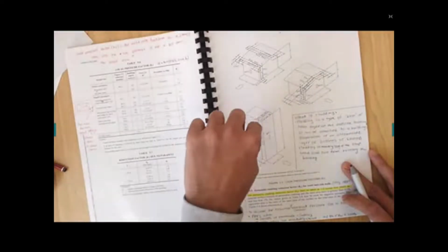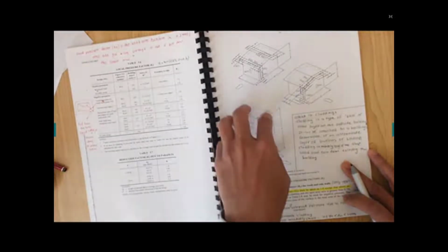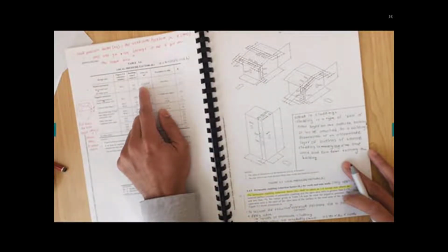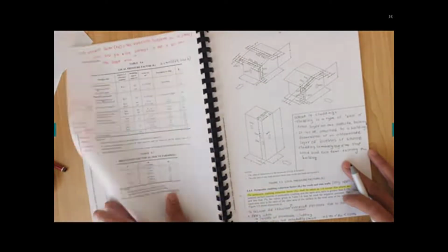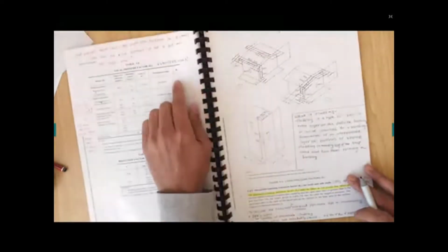The open area ratio is the ratio of open area of the surface to the total area of the surface. Figure 5 shows the dimension of dA. KL is the local pressure factor. When you want to calculate the pressure on a small area, not the whole structure or the whole wall, but any particular small area like a window or door, you consider the KL. That's the condition here: area is less than 0.25 a squared, and for the a value you can calculate the minimum of 0.2b, 0.2d, and h. We have taken examples where you consider the KL, like in the lectures, where we have a KL value of 1.5.